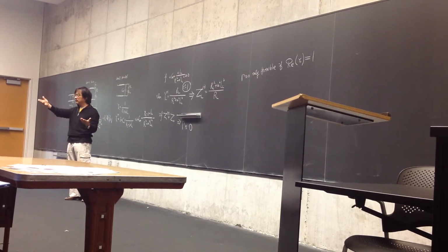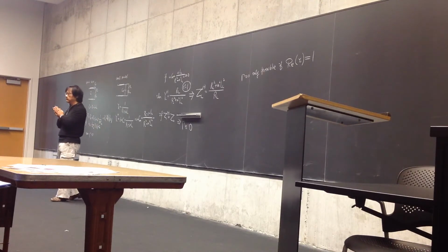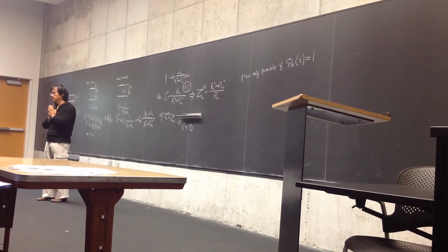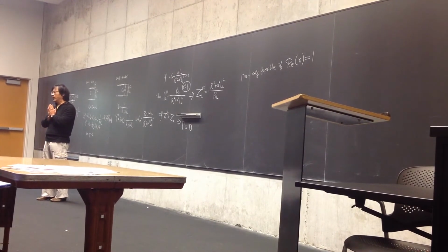So the first condition is met by changing the value of your circuit component, your capacitance or inductance, to cancel. Then the second condition is if your Z0 doesn't happen to be your RL, you move your component along the line, by the right wavelength, to the right location where the real part of your admittance equals 1.